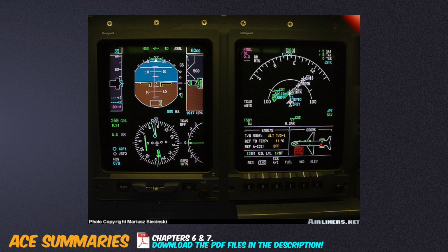Advanced flight instruments. The EFIS is a fully integrated navigation system which uses digital displays for EADI, Electronic Attitude Directional Indicator, and EHSI, Electronic Horizontal Situation Indicator. Other parts of this system are the EFIS controls panels and symbol generators. These systems display the same info in a clearer and more versatile manner, bringing together additional data from different sources to present the pilot with the best navigation information possible.